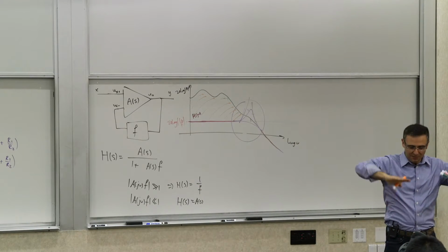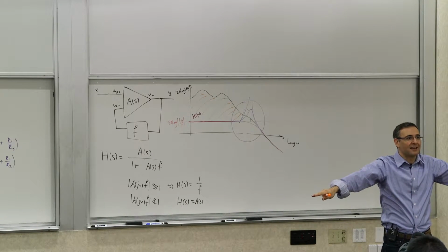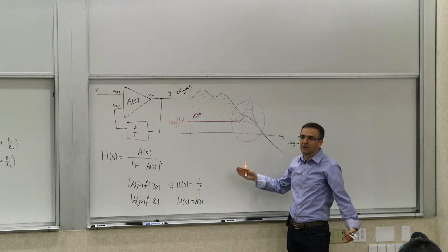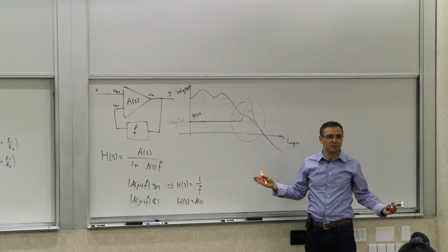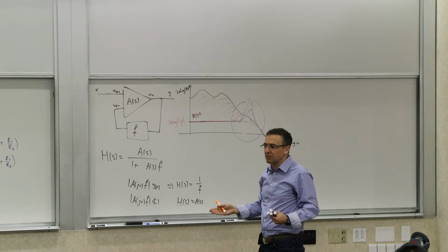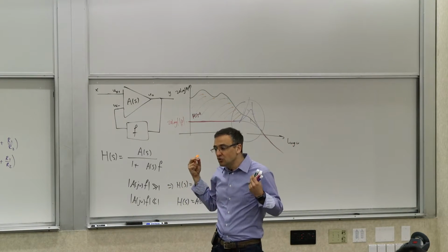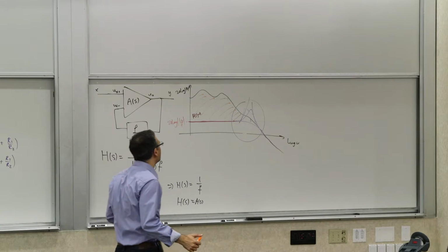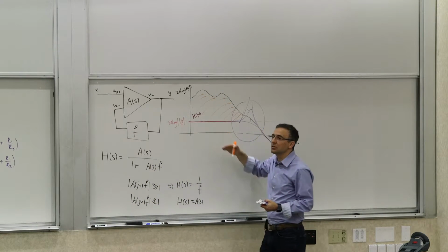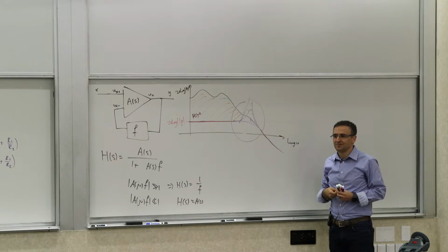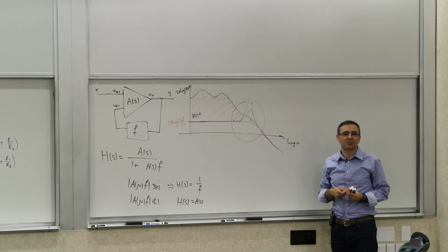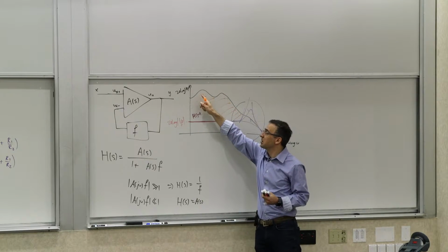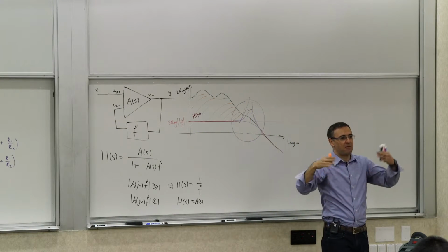Yes, it increases the bandwidth, but basically just by getting rid of that gain. Now, you may not need that gain, and that's perfectly fine. Then you basically use feedback to enhance your bandwidth. And I'll show you a simple example right after this. But in general, you have to realize that the bandwidth enhancement that you get from feedback is because you're just basically reducing your gain to a level that you can sustain in a constant fashion. But it does also other things. You can see that it removes these non-idealities, these fluctuations and variations.